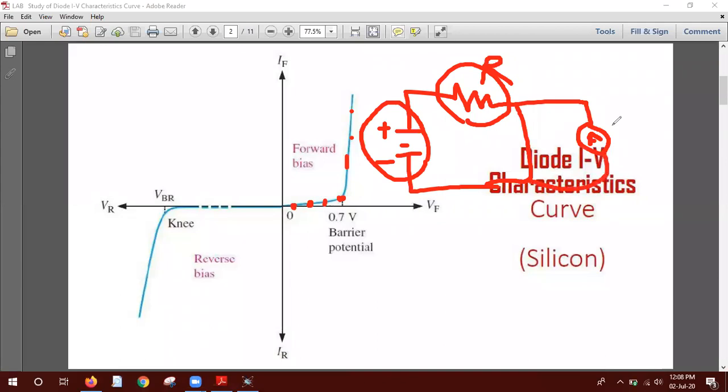What will be that? Ammeter, there is a small resistance in the ammeter. We all know that when the current flows, if I connect it in parallel, the current will divide. The current divider rule, the KCL rule in the node. Do you know? Yes, the current will divide, so we will not get the exact current. We'll only get part of the current from the ammeter.